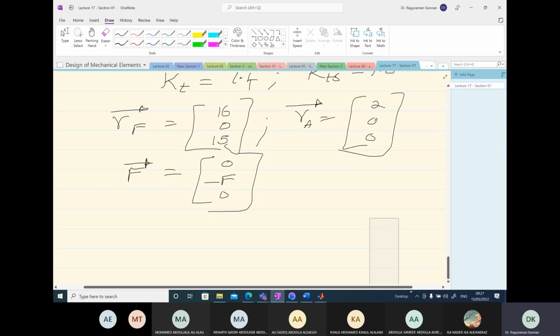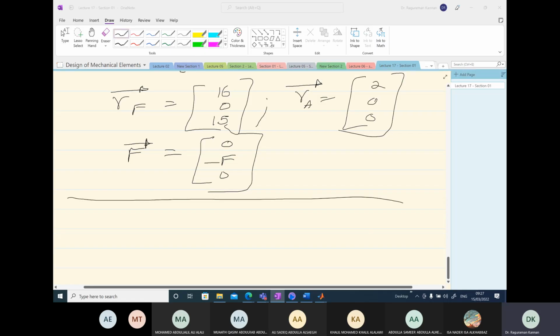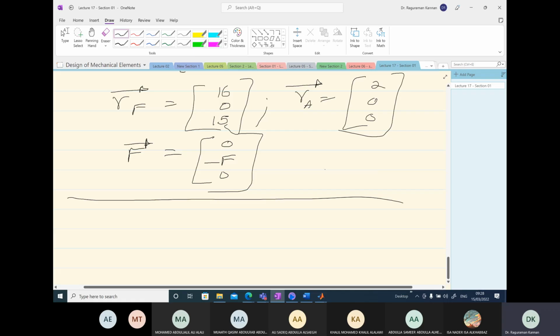Remember, we also have a shear force. But if we have a torque acting on the stepped shaft here, then we can neglect the transverse shear force effects, and then do the calculation. So first let's calculate the moment with respect to A due to the force F. It is going to be RF minus RA cross product F.